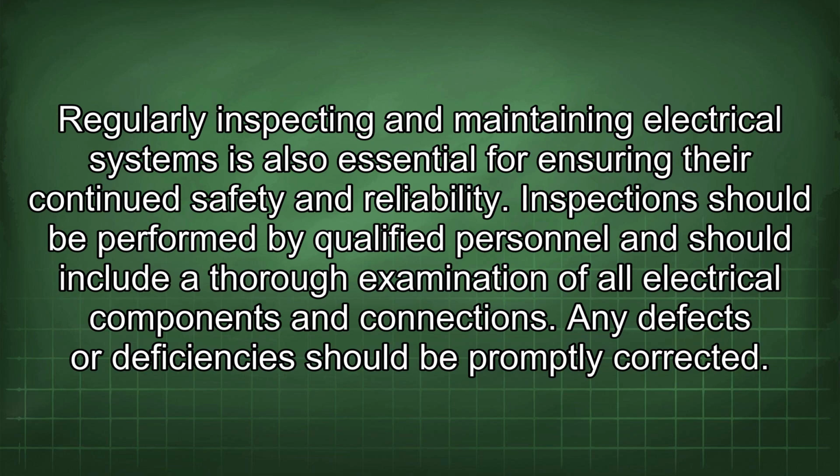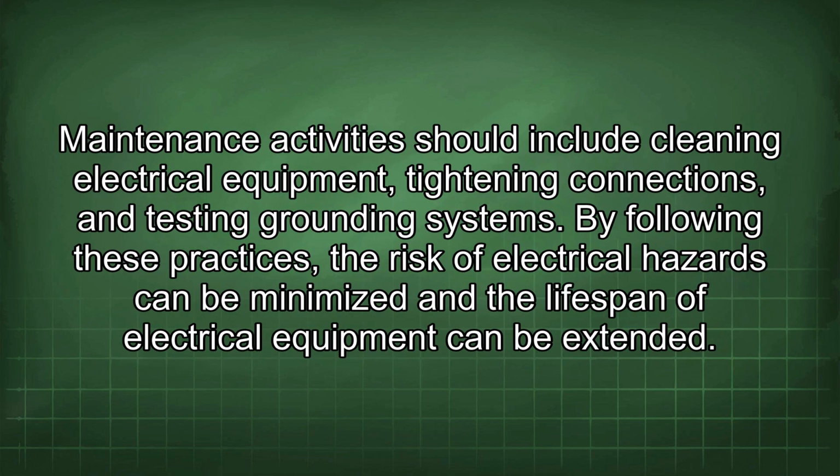Inspections should be performed by qualified personnel and should include a thorough examination of all electrical components and connections. Any defects or deficiencies should be promptly corrected. Maintenance activities should include cleaning electrical equipment, tightening connections, and testing grounding systems. By following these practices, the risk of electrical hazards can be minimized and the lifespan of electrical equipment can be